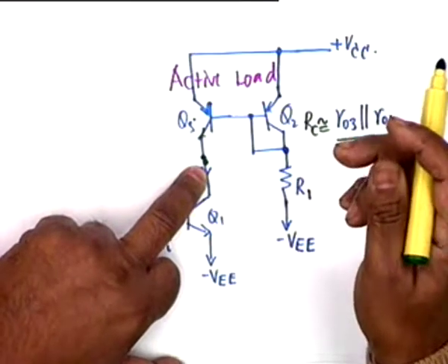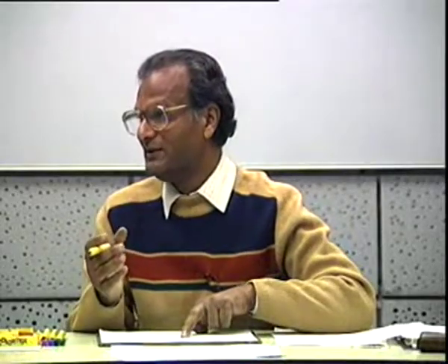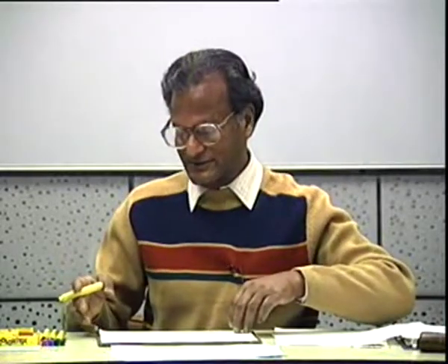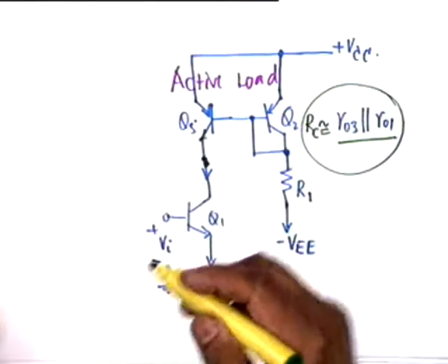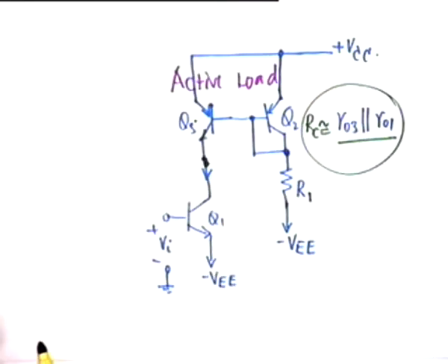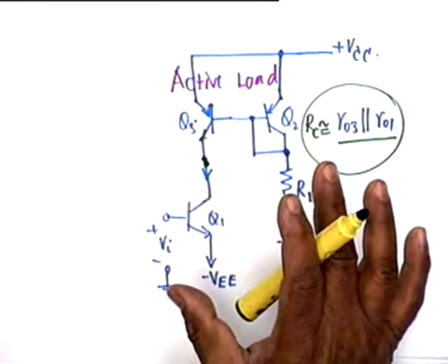They are interchanged in some circuits where it's not very critical, but where it is critical, it is better to use a PNP and NPN. And as I said, NPN and PNP in the same chip is no problem, and they can be matched absolutely identically.